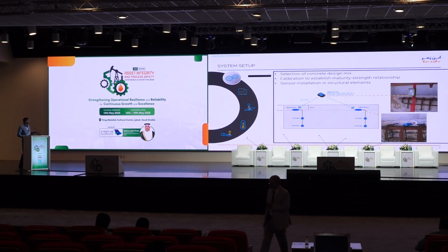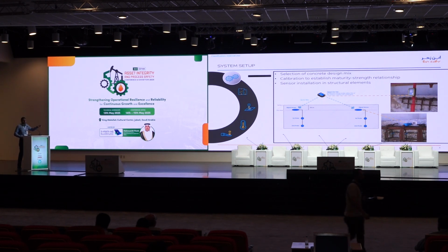Now we will move to the system setup. It is very, very simple and depends on the sensor. We put the sensor on the top layer of the rebar, and it should not exceed 100 mm. Because it depends on Bluetooth, you can collect the data through our mobiles. The data is sent to the platform, and we can visualize all the information, the temperature and the strength, through the platform.